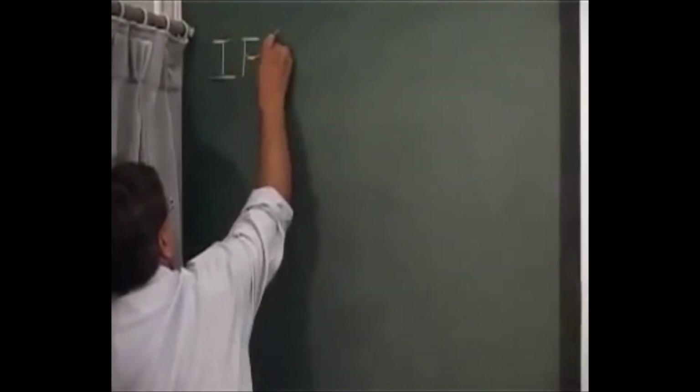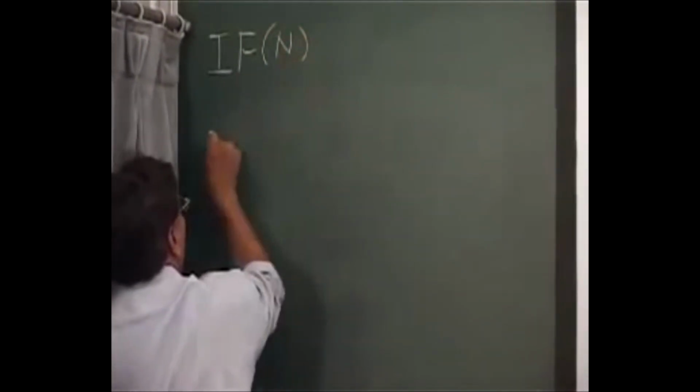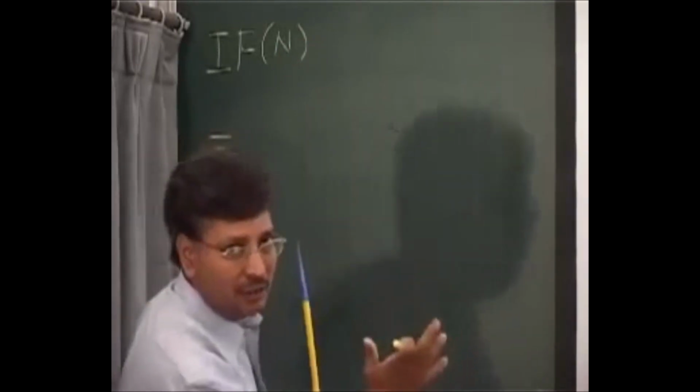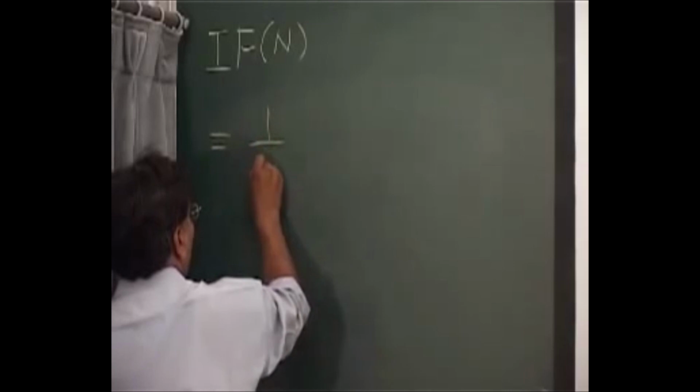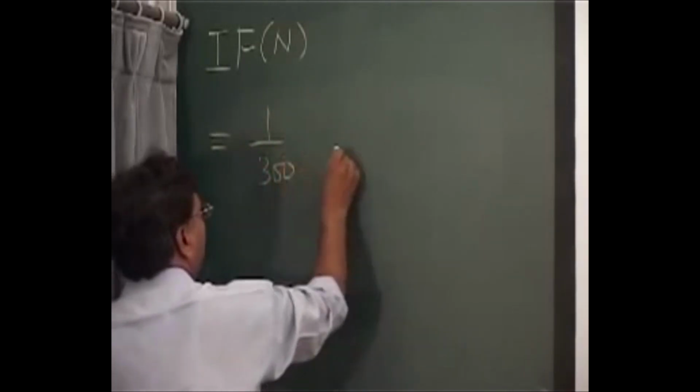Evolve an impact factor for each direction based on a linear sum of the inverse of the mixing height. So I'll write the impact factor for direction north. The first term is the inverse of the mixing height, and whatever units are given you don't have to change, so 1 by 300.